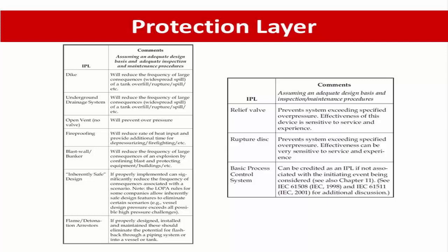Next IPL is the underground drainage system that can also reduce the frequency of large consequences. Or an open vent, which can prevent overpressure.